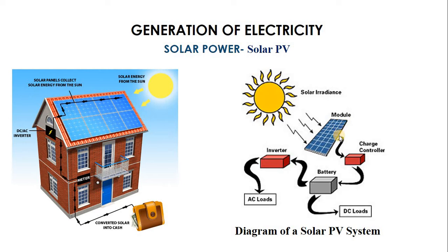Because the output of the solar module is supposed to usually be higher than the power of the battery in terms of voltage. In order for this module to charge a battery, the voltage should be higher than the voltage of the battery.